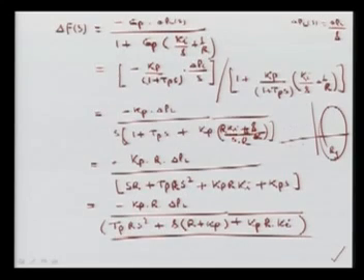If we solve this, the equation which we wrote here, I can write the Tp R S square plus S R plus Kp here plus your Kp into R into Ki is equal to 0, and then we can solve this square term.